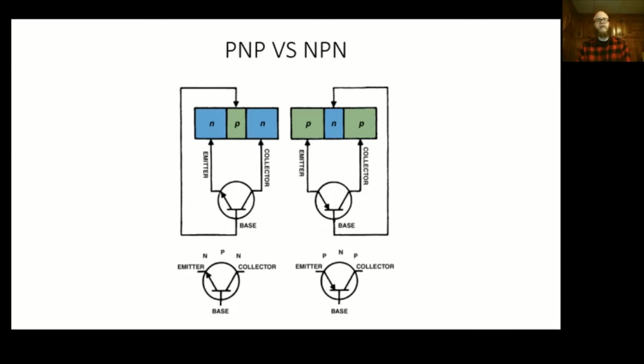So when we get to transistors, you can see that there's a lot of similarity there. We still have P-type and N-type, and we still have symbols on here that look like a diode, right? The arrow points in the direction that current will be allowed to flow. And this is conventional theory current, so the stuff that we're used to dealing with. And if you take your meter and you touch the red meter lead on the base and the black meter lead on the emitter of this NPN style transistor, it would show us what the bias voltage is required to flow current through that, which in most of these is about 0.6 of a volt, just like a regular diode would be.